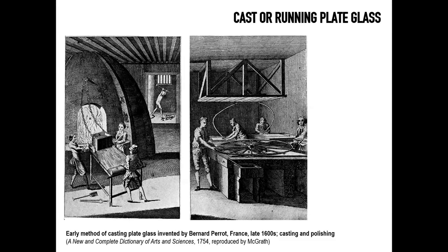It consists in the casting of glass onto a tray that is rectangular, that has a certain depth that is determined by the glaziers. Once the glass is cast directly, when molten, onto this plate, the glass is rolled with a heavy cylinder that puts pressure on it and reduces it to a fairly consistent thickness, not necessarily perfectly flat or parallel, but a rectangular shape that can then be polished, for example, or ground to reduce the surfaces of glass to two perfectly parallel surfaces that allow maximum visibility through it.